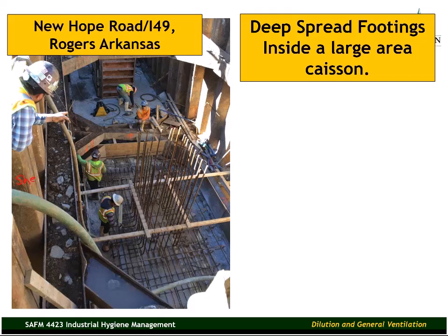Sheet piling. These are steel sheets driven into the earth. We drive in all these steel sheets, and then we excavate out inside of that steel sheet structure. Then once we get deep enough, we can go in and start building our reinforced concrete footings for the bridge. In this situation, you have the potential for poor airflow, not good adequate natural ventilation.